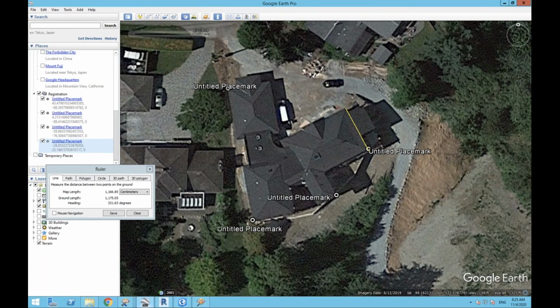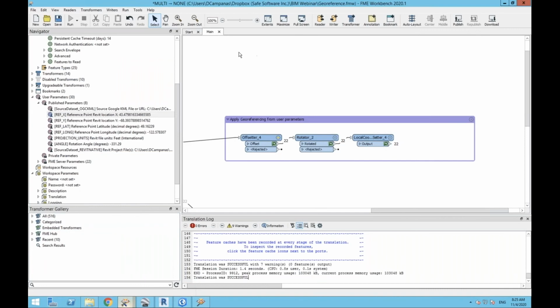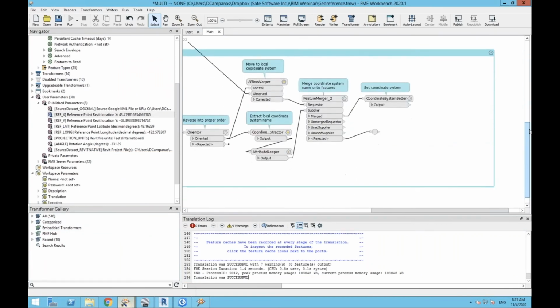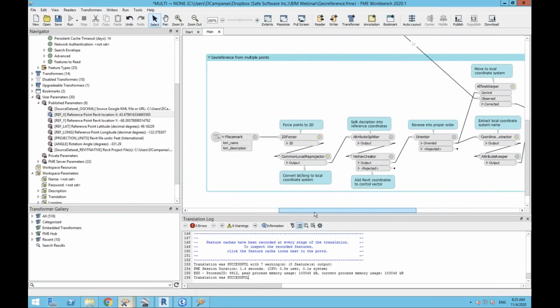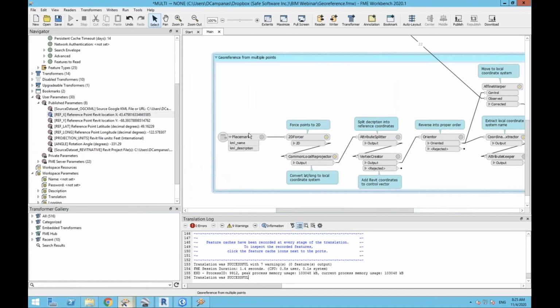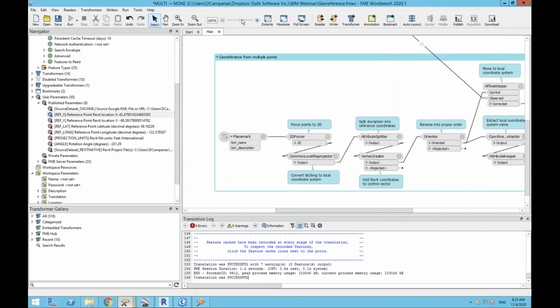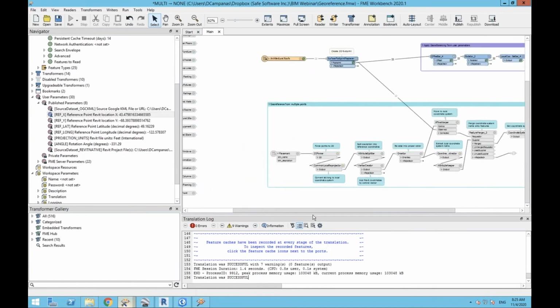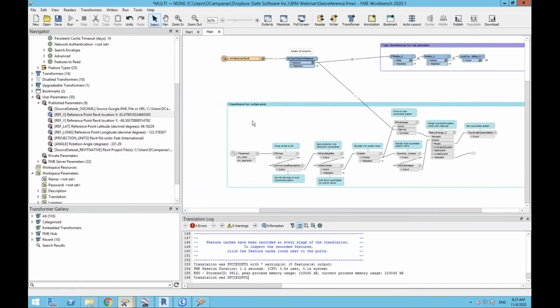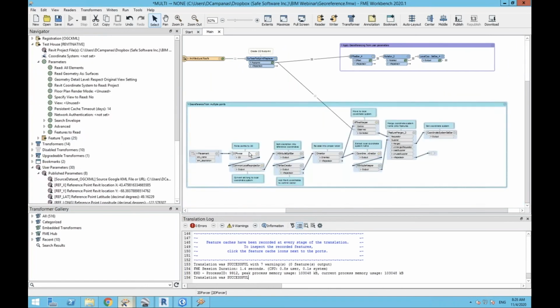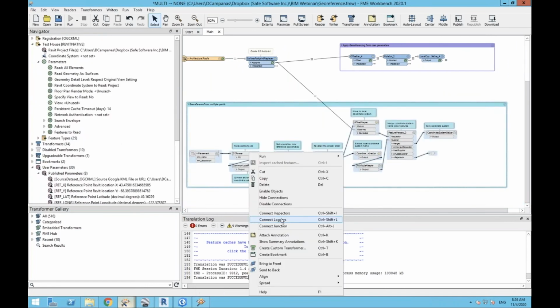Now we can refine this a bit because this heading is only to 2 decimal places and you're only using 1 place mark. There's probably another way that we can be a bit more accurate. And that way is, instead of a single point and angle, we're going to try grabbing a bunch of points here. Let me just zoom out and enable this part. So what we're going to do is use multiple points and calculate an affine transformation to fit that into place.